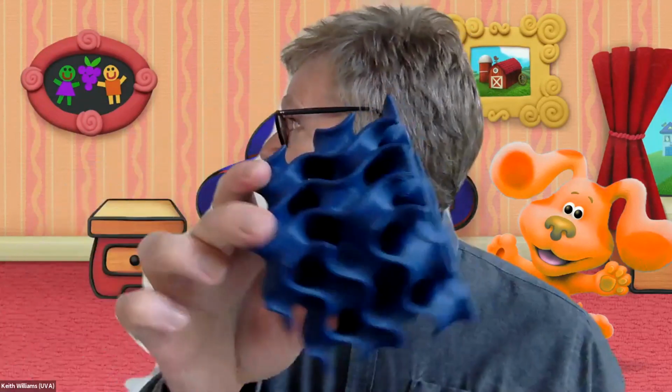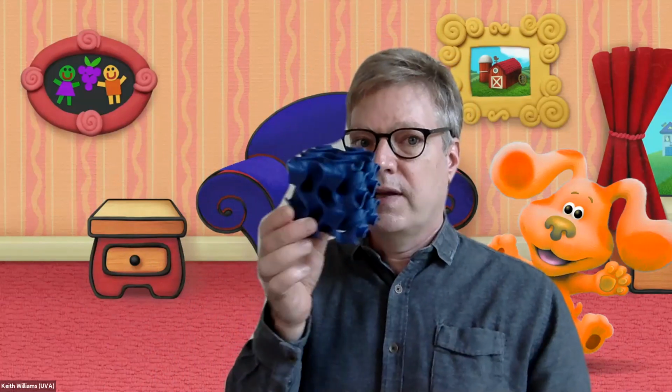It's a plastic object that you could think of as like a bunch of beams that go this way and then a bunch of beams that go this way and then that way and that way, like a waffle, sort of an alternating waffle kind of design. But it's three-dimensionally connected. What makes this design so really special is this is not something that you could make subtractively. Subtractive manufacturing means, suppose you get a block of material and you just chisel away at it. If you try to make this thing that way, good luck. It's a very complex three-dimensional shape with a whole bunch of voids and all that. So this is a really nice example of something that you pretty much can only make by 3D printing.